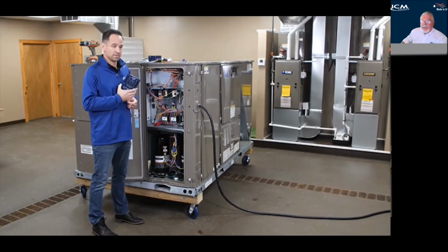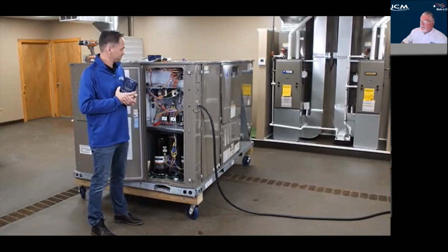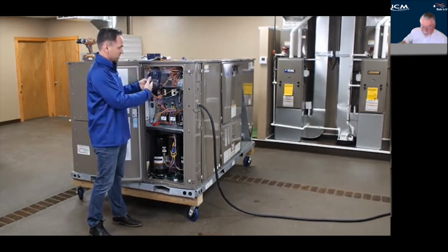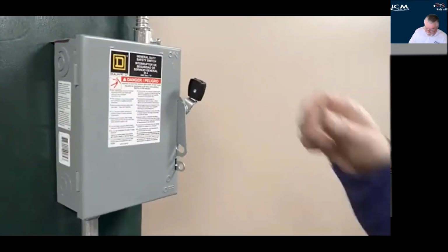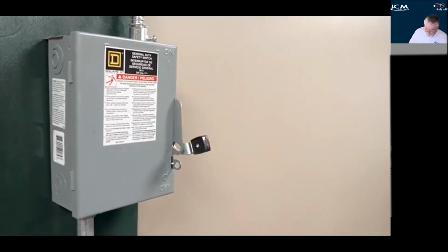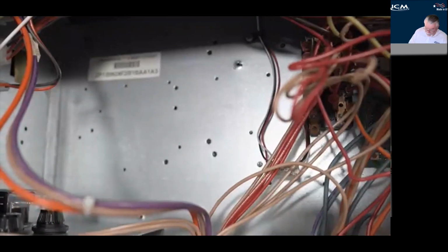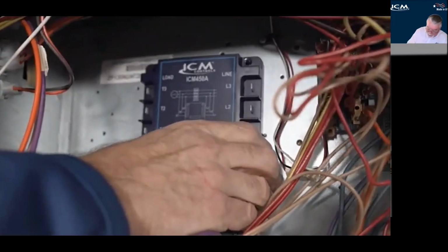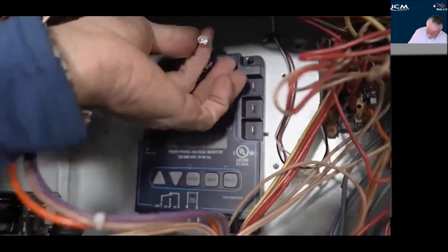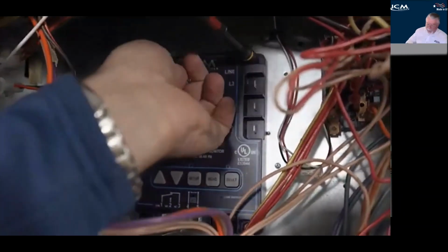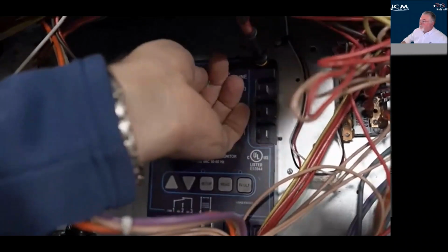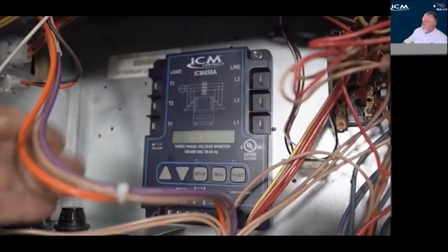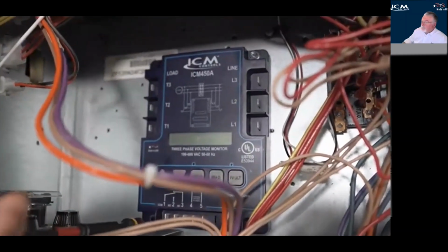So I'm going to go ahead now and install this on this 10-ton rooftop. All we need is a clear space to put it. I have to put some pigtails on it, a couple screws. Keep in mind safety first, so you want to make sure you turn the disconnect off to the power source for your unit. You want to find a big enough area to set this in comfortably. Get your hands out of the way. Easy to work on, easy to see. The unit does come with self-tapping screws to make it easier to go through the sheet metal.